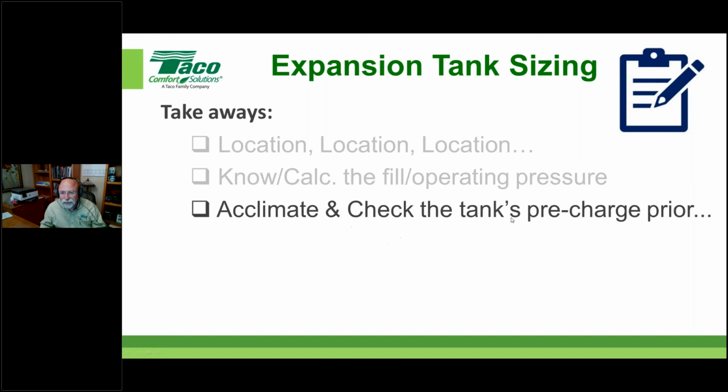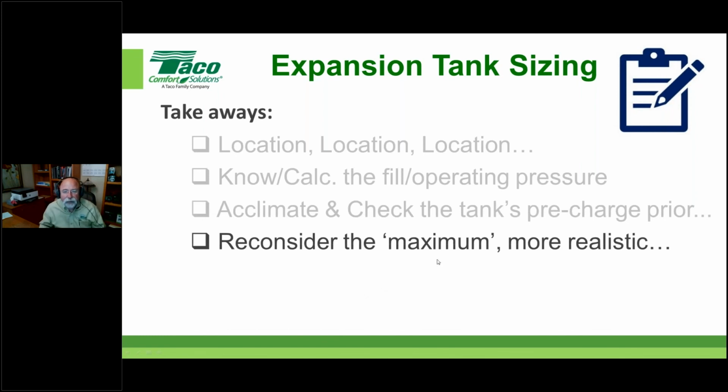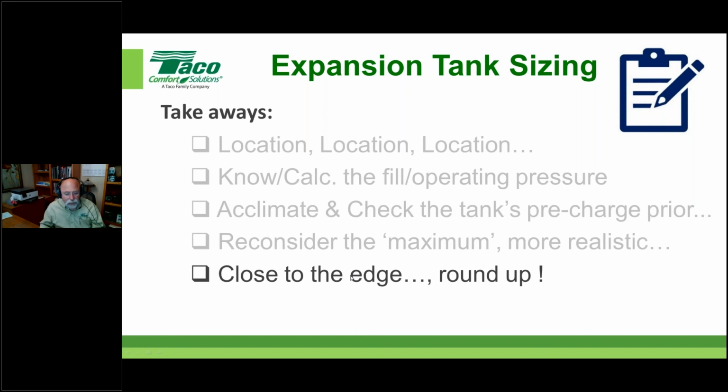Acclimate and check the tank's pre-charge pressure, or your football. Okay. Just remember, prior to installation, prior to being on the field, make sure it's right. Okay. Reconsider the maximum more realistically, right? That maximum number is what I've kind of harped on. I want you to think about that. Okay. Hey, with expansion tanks, if you're on the edge, man, round up. I think you got that. I pointed that out on the handout, as well as I've said it a couple times now. Just round up. Okay. It's not going to hurt you.